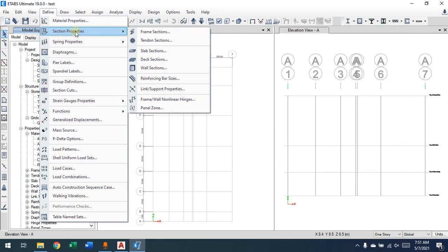Now if you remember from structural analysis 2, that you have indeterminate structure, one of the key points in analysis is the structural stiffness and the member stiffness. You cannot analyze a structure if you don't know their stiffness. We had two methods there, which we call approximate analysis and accurate or proper analysis. In order to do a proper analysis, you need the beam section size, in order to calculate their stiffness, and the column size.